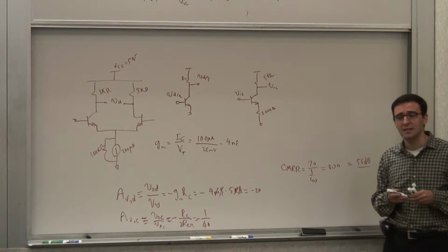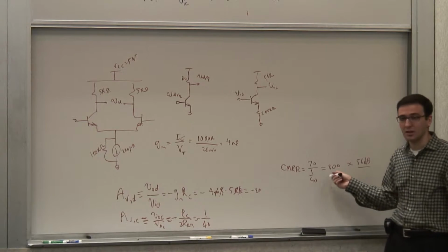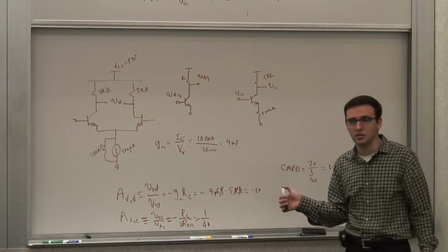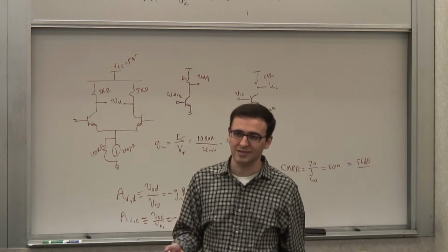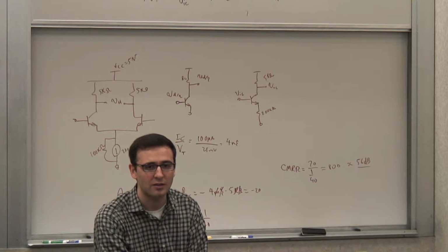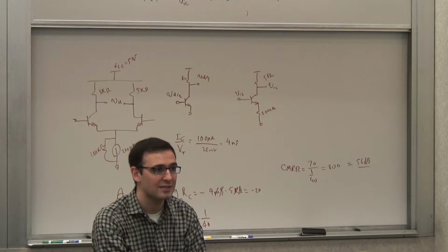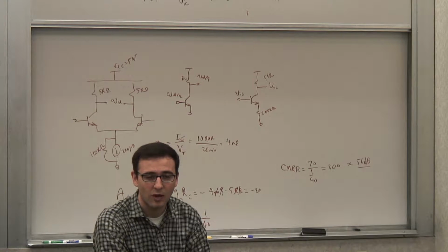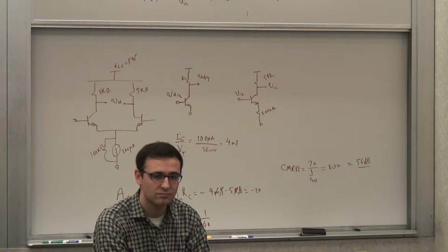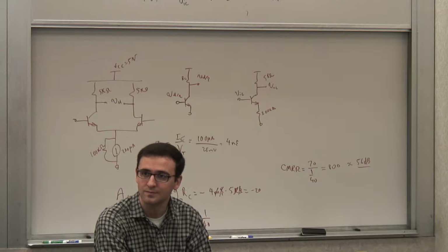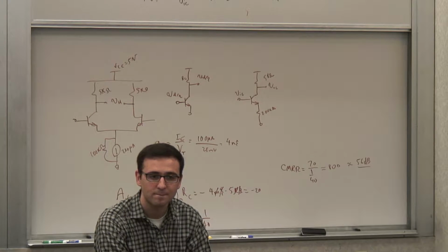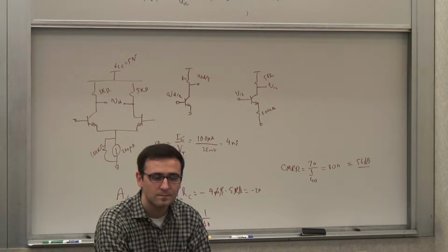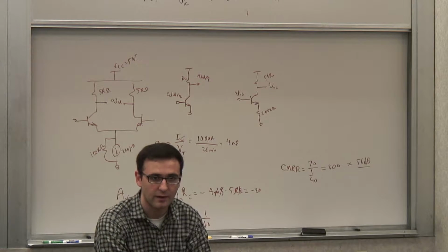And you see that even in this case, although this appears like a lot, if you look at the common mode rejection of many op-amps, they're in the order of 70, 80 dB, or even higher for op-amps with higher common mode rejection. So you can see that they substantially attenuate the common mode signal while they amplify your differential signal. And this is good for input voltages in the range of 0.1 volts. Right, correct.